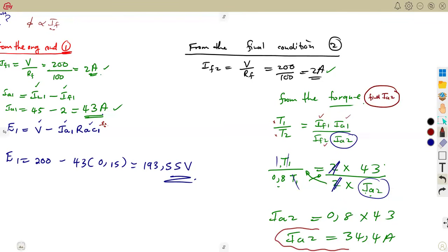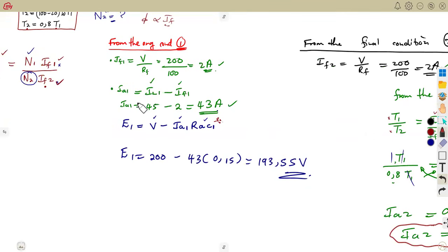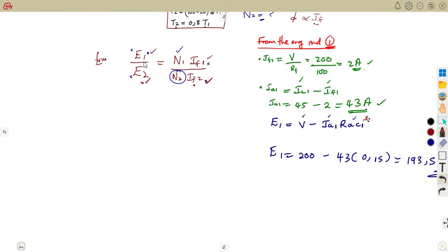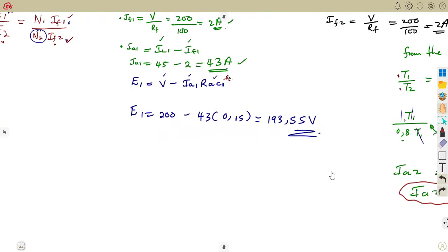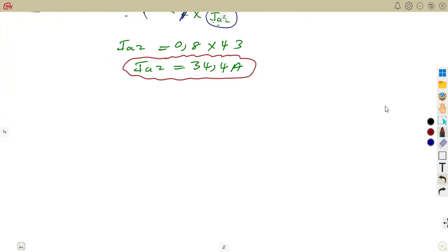With the 34.4 amps, which is our armature current, remember, we're supposed to just use this way, but we're limited because we're not having the load current. And why are we calculating this as if it is needed here? It's not needed. It is E which is needed here. It is that E2 that is needed. So calculating this is so that we can calculate the E of the final condition, the generated EMF there. So E2 was going to be calculated.